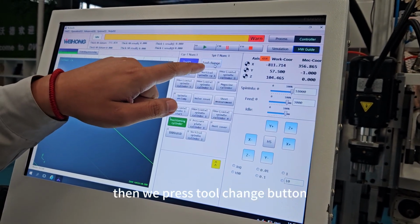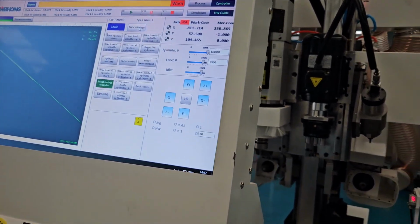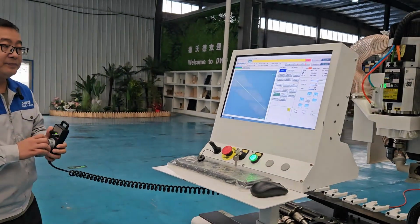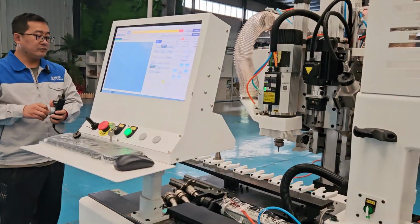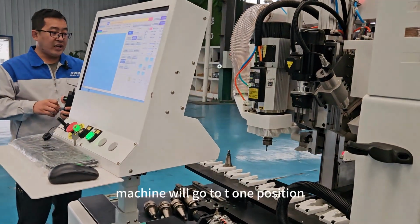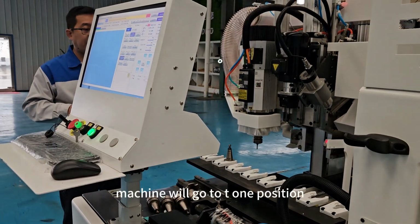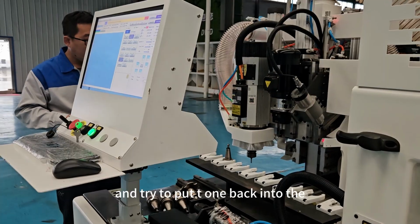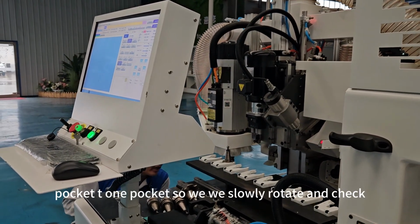Then we press tool change button. After that, we rotate this one. Machine will go to T1 position and try to put T1 back into the T1 pocket.